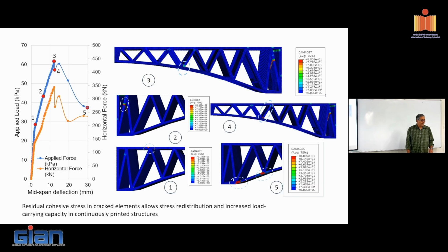One question. Can we not remove all the tension members, put steel tubes and bolt it? Yes and no. Initially we designed it as a tied arch, to the point that we even printed it, leaving holes so that we could insert these tension ties. And then somebody said, wait a minute, if it's a steel tie, it's going to rust and fall apart. So then we said, okay, we'll change it to carbon. We'll go to a carbon tie.